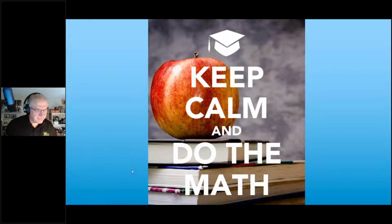Now, great question from Jesus. Does the difference between PEX A and PEX B have any significance? No. It's not differentiated in any of the manuals that I've seen. So PEX A, PEX B, PEX C, no difference whatsoever. Any PEX manufacturer is going to tell you that hot chlorinated water at high velocities and continuous circulation is the kryptonite for PEX.